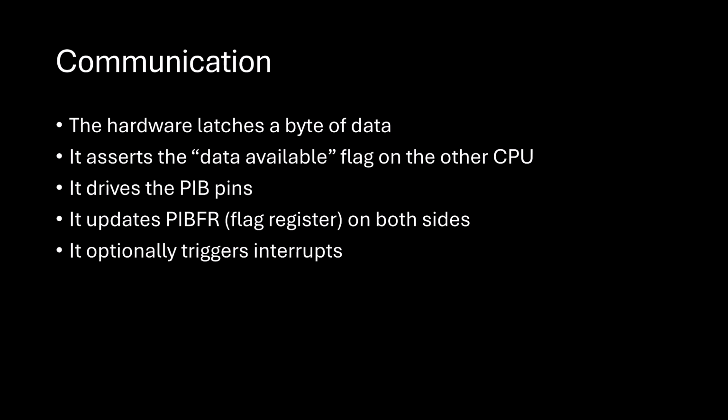It's also managing a flag register on both microcontrollers, kind of what's going on with PIB. And you can optionally use interrupts. That's definitely the way I want to approach it, is to use interrupts. I can't imagine having something sitting there polling for the status to change. So interrupts is definitely the way to approach this.